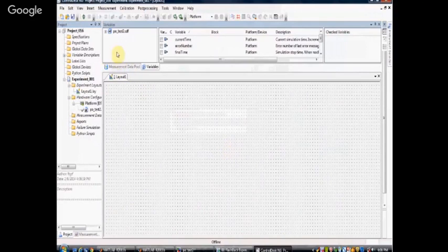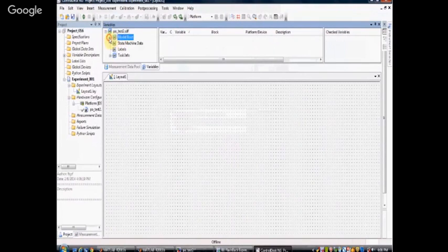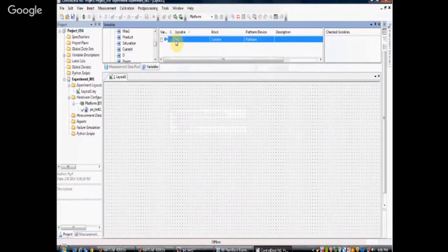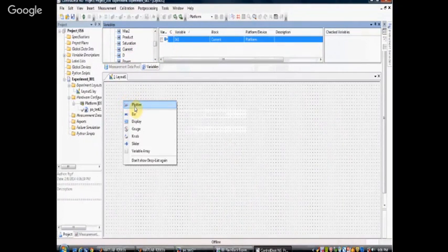So here you can see p_test.sdf is here. Click on that. Model root will be there. In that model root, click again and choose whichever parameter you want to see. You want to see current, you want to see voltage, whichever parameters you want to see, just drag and put into the plotter. You can plot the thing.